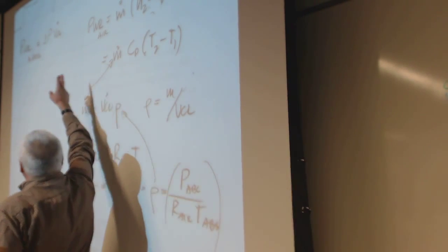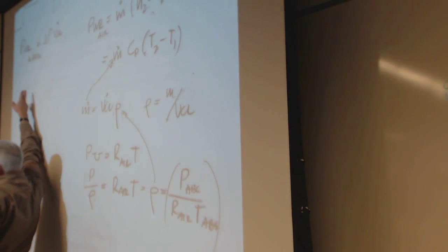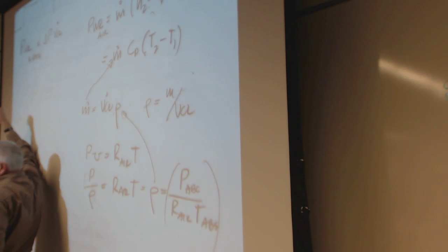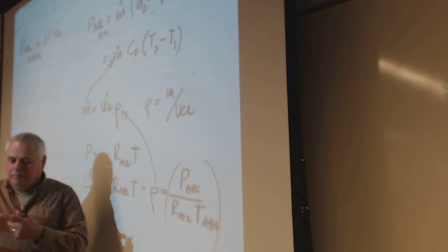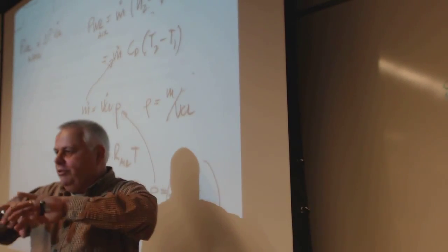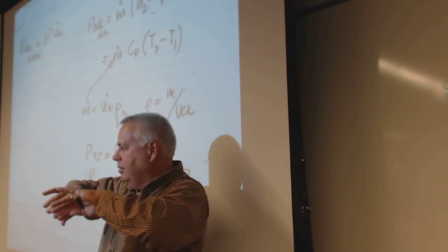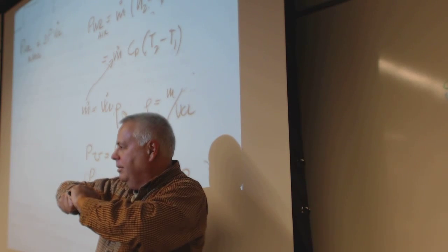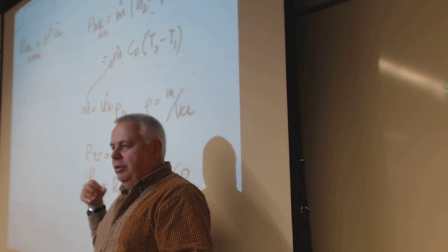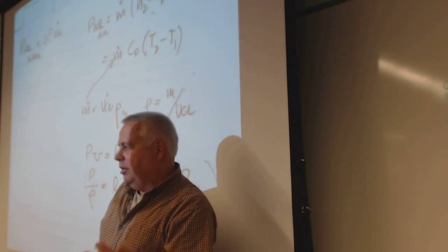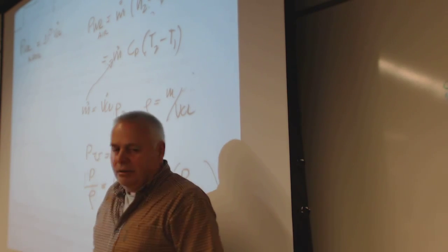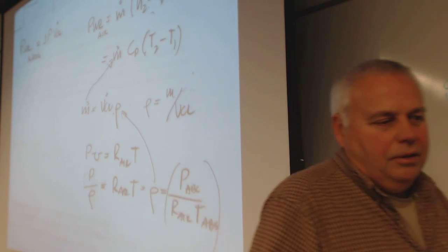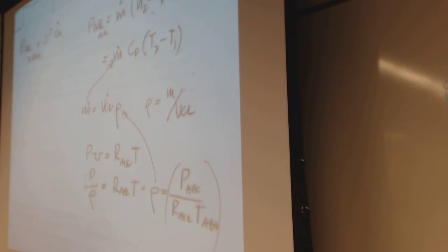That's power in, and this is the power out. We can find an efficiency for the entire system of the air motor and the pump. We can't separate how efficient the pump is and how efficient the motor is. They're bound together. But we can say we put this much air power in, it turned into this much water power. And we do that at different RPMs for each group.